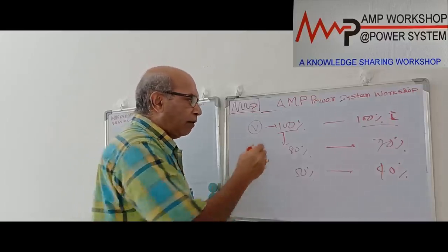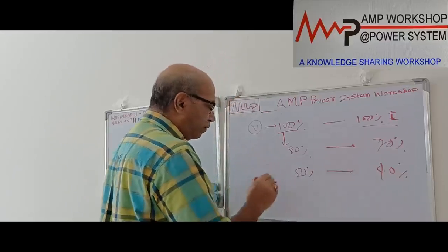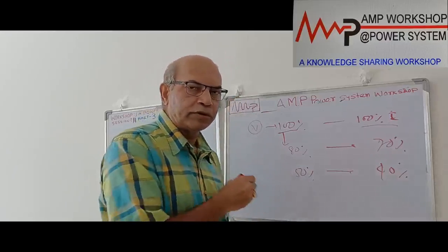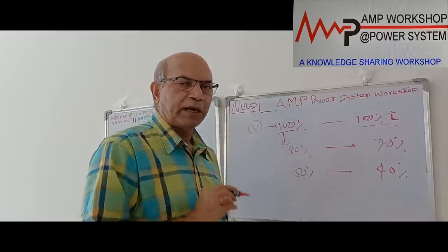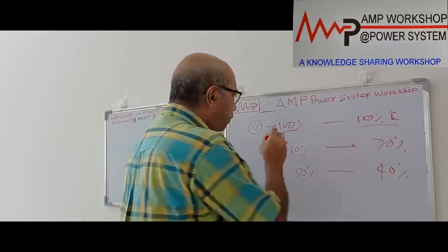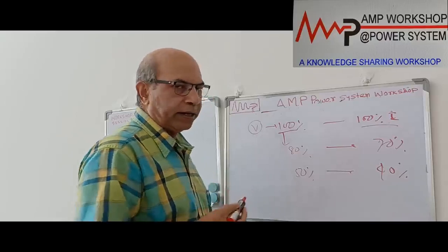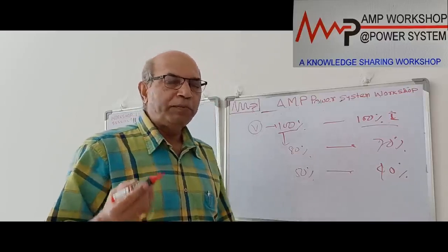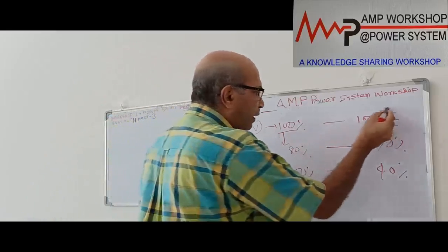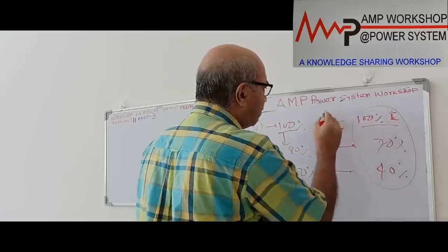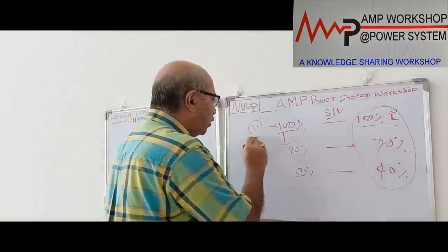So that means the operating current is not fixed. In the case of the normal conventional differential relay, which was just shown in the previous characteristics, the operating current is constant. But if we can provide this type of bias characteristics or restraint characteristics, the operating current will be dependent on the fault current. In the case of the 51V relay, the operating current is dependent on the voltage.